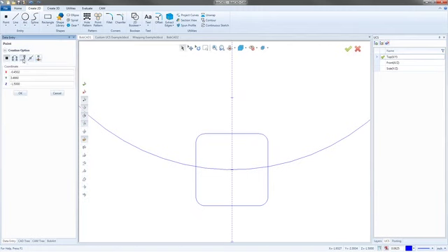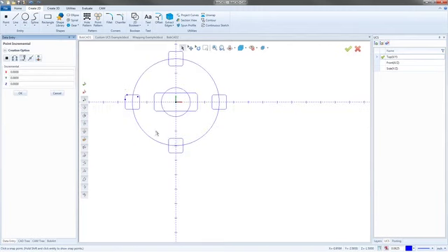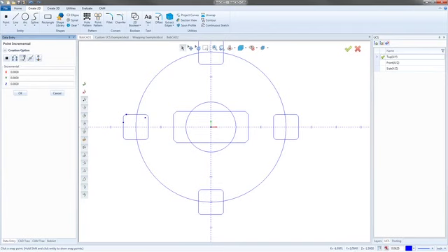The next function we have is pretty standard. It's our incremental function. So if you have a point, well, really, let me explain. The difference is with the sketch enter function, every entered point that I define, so if I say put one at x1, y1, it's based off of this location being 0. So it puts my point there. When we get into the incremental function, we're no longer looking at that point in the middle. We're not looking at the origin of the BobCAD actual CAD software. We're picking the 0 location is essentially what we're doing.